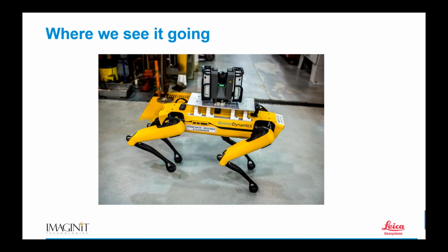We see a lot of this information. The big thing that we're seeing is a push toward digital twins. The more information we can capture, the more accurately we can build these existing models, the more accurately we can utilize the digital twin. Software like Tandem, being able to put in the IoT sensors, monitor equipment, monitor whether lights are on, occupancies. We can now start utilizing that digital twin to turn off lights, to control the building, get readings from equipment. If a fan motor is running at X and it starts to have problems, the report's going to tell us, hey, you're starting to lose some efficiency here. You may want to go check that out. So there's a lot we can do.